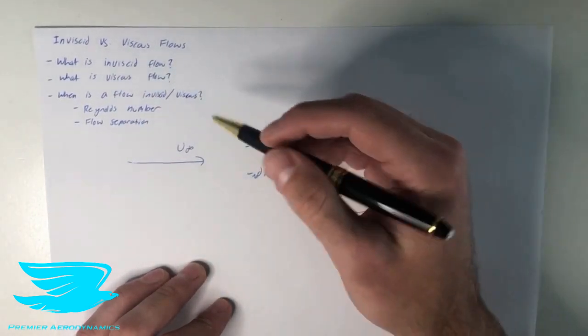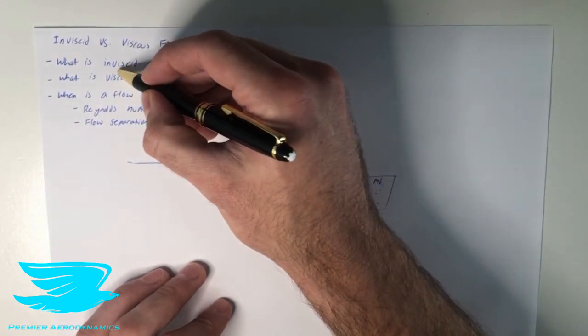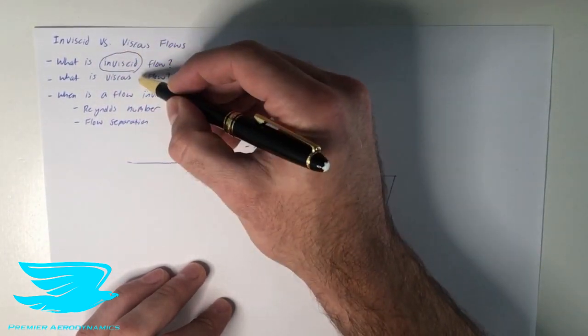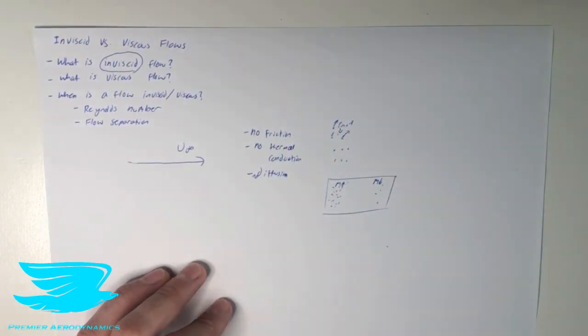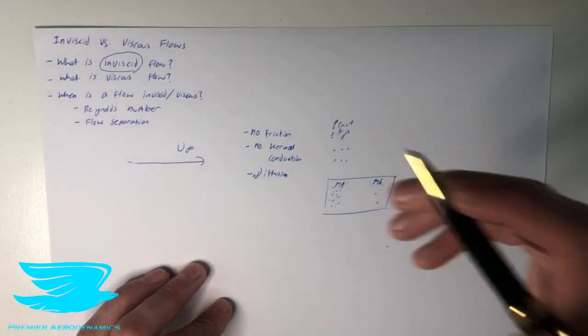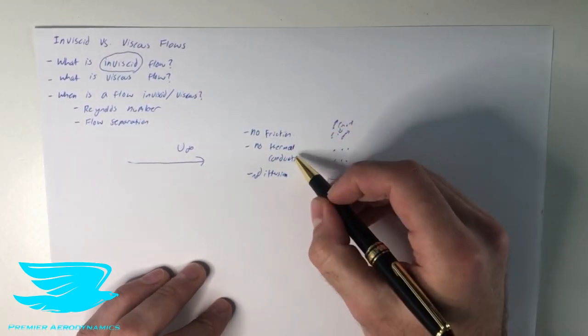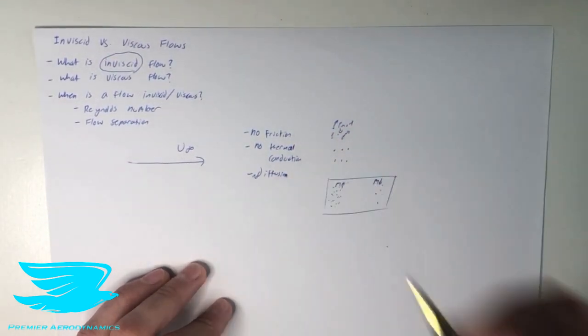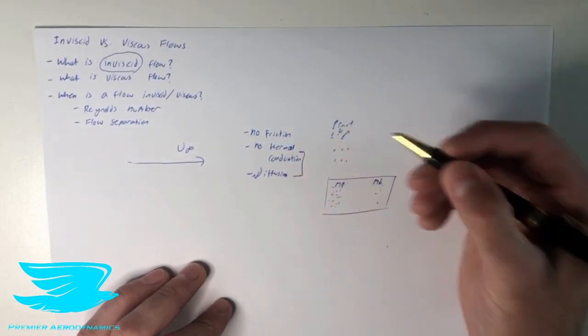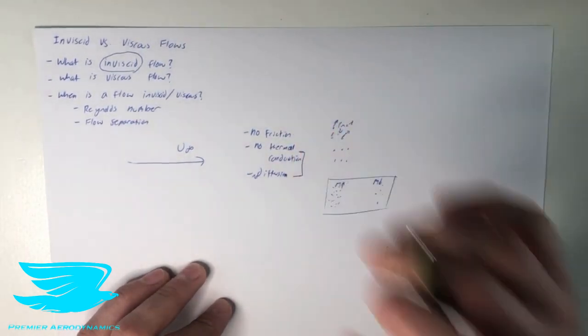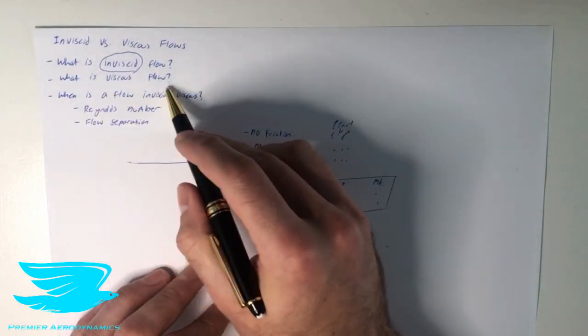The reason why is because of the term. The term inviscid, we often just associate with viscosity, and that just reminds us of friction. So whenever we say no viscosity, or when there's an inviscid flow, we think, okay, there's just no friction. But it also means that there's no thermal conduction and no diffusion. These are two very important parameters, and it's important to remember these two. Now, what is a viscous flow?